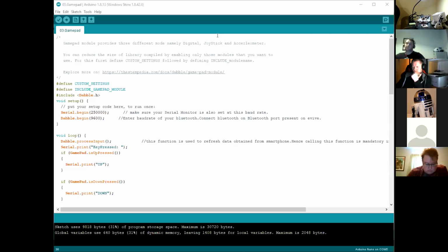The servo library uses interrupts to do that calculation, so it's a hell of a lot better, and you do get good results. The problem is that it's interrupting every time you want to do that signal that's out there, and it puts a lot of overhead on the overall processor, which is one of the reasons why I wanted to play around with the ESP32, because the ESP32, in my experience, takes it in its stride. It is fantastic for controlling servos. Rightio.